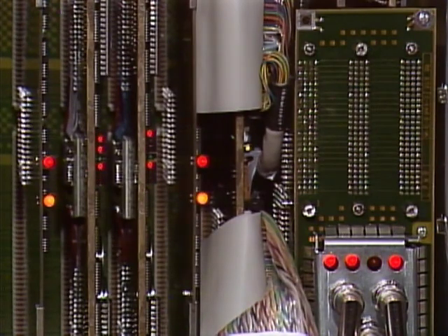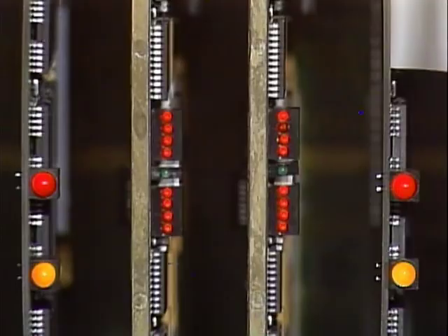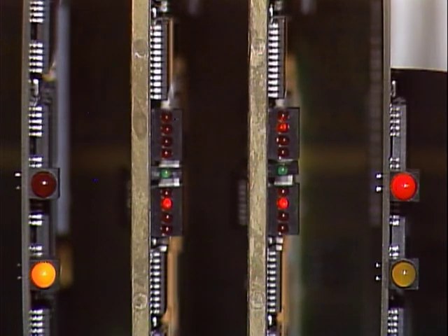Another method to determine problems is by observing the pass-fail LEDs on the modules. Each M-Bus module has at least one LED that indicates the results of the self-test diagnostic. Most modules have a green LED that is illuminated when its self-test diagnostics have passed. On the memory modules, the LED that indicates successful completion is amber. Failure of any pass indicator to light means that the module has failed its self-test diagnostic and should be replaced.